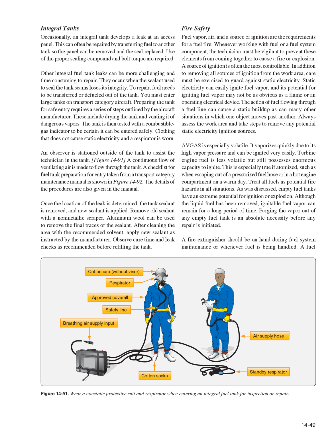As was discussed, empty fuel tanks have an extreme potential for ignition or explosion. Although the liquid fuel has been removed, ignitable fuel vapor can remain for a long period of time. Purging the vapor out of any empty fuel tank is an absolute necessity before any repair is initiated. A fire extinguisher should be on hand during fuel system maintenance or whenever fuel is being handled.